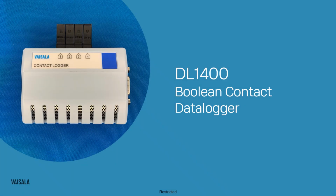The Boolean Input Data Logger is actually both a temperature and Boolean Input Data Logger, depending on the order configuration. The specific one that we're going to look at today is the Boolean Contact version, and that looks a little bit different than its other configuration of the DL1400. It says contact logger on it, and it has numbered inputs on it. The temperature version is, of course, going to have temperature data logger on it, and it'll have thermistor sensors.